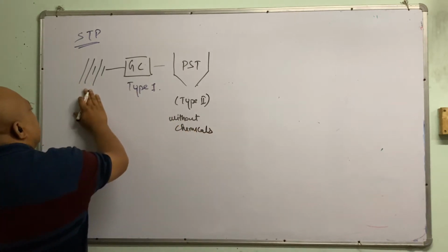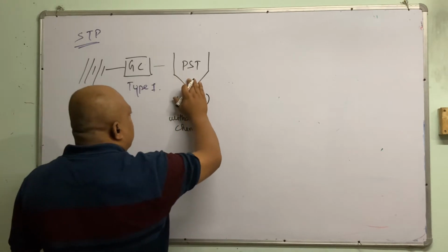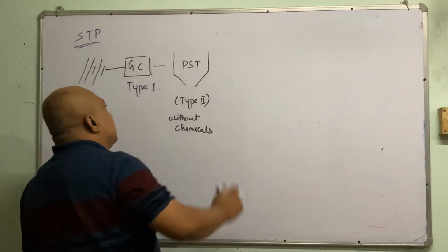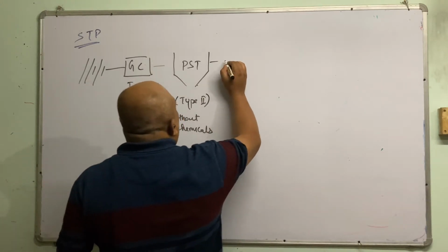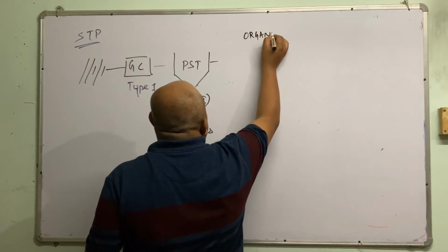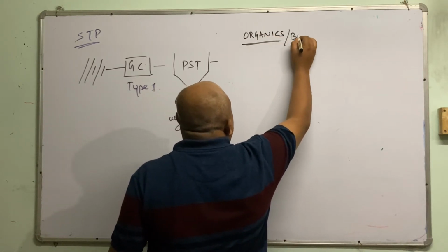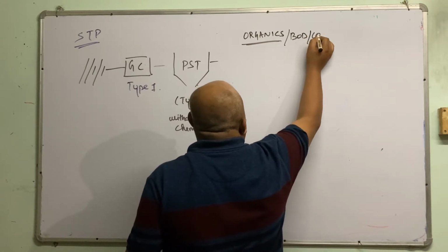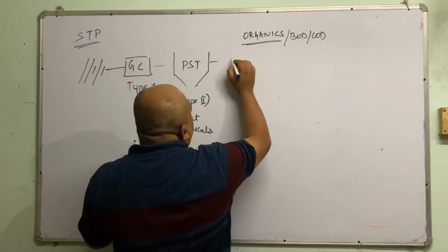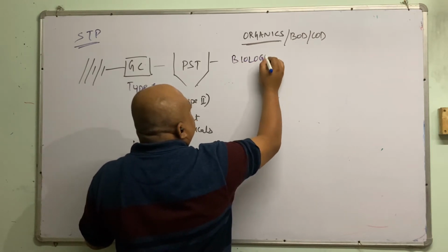Now the floating materials are removed, the grit particles are removed, the total suspended solids are removed, even though effectivity may be different. Our next target is to remove the organic load. Next one is to remove the organics, that is the nutrients, that is the BOD and COD. This is called the biological process.